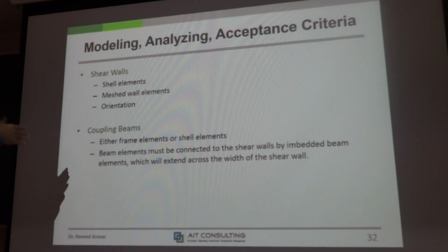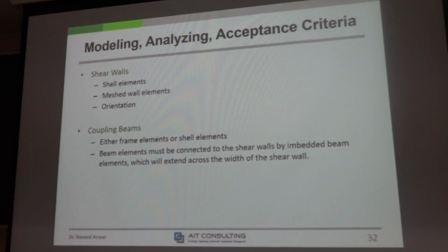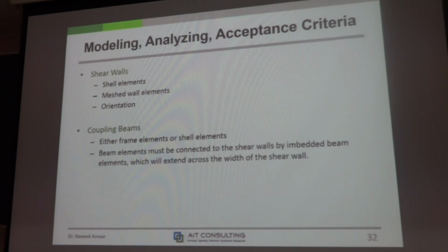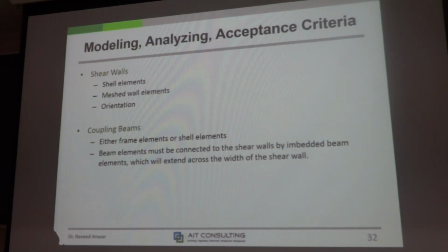Now, to be able to do all of that, obviously you will need to understand all the details behind each decision, because each decision will take you from this way to that way. It's so different. Rigid diaphragm, you go in a very simple way, your model becomes very simple, with much less results. You choose not rigid diaphragm, you go another way. Much more complicated, but much more useful. Right? So every decision will give you more information, but will increase your work.